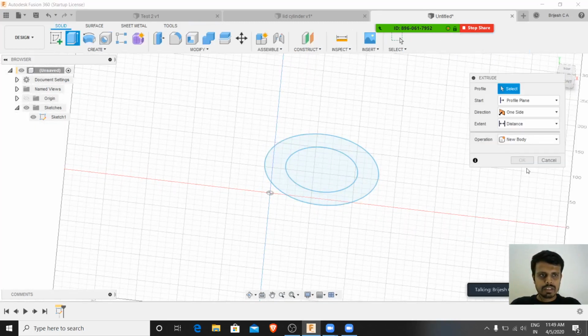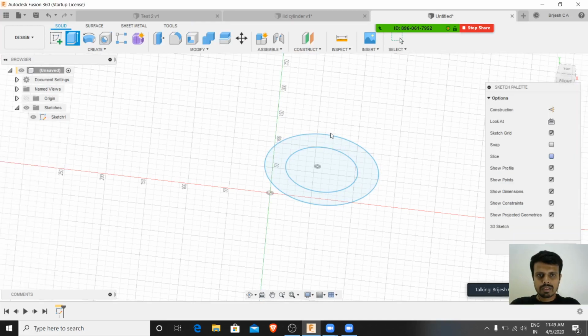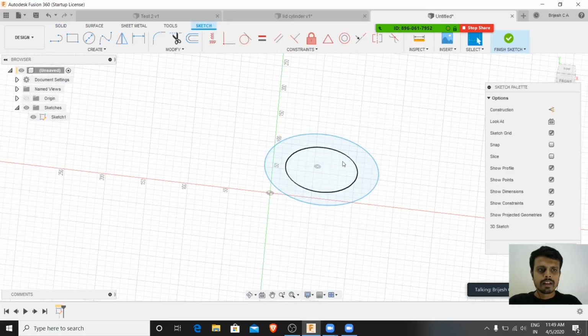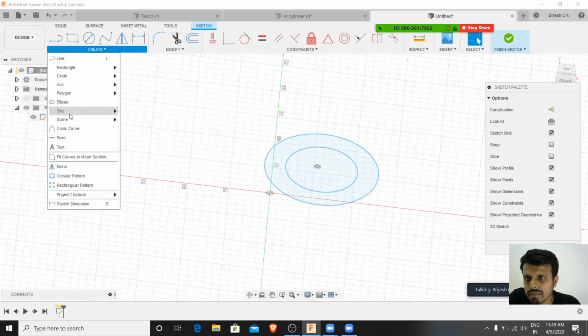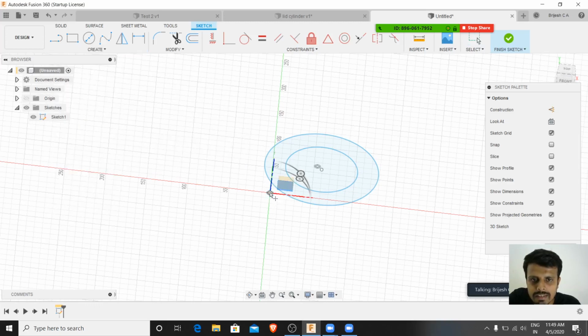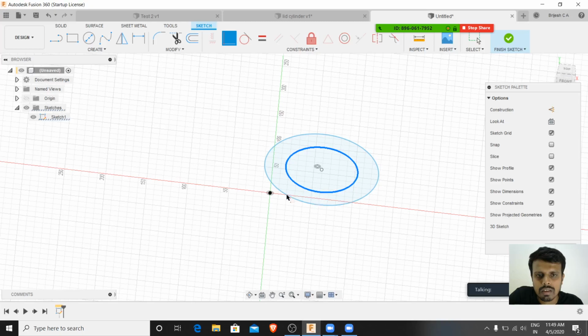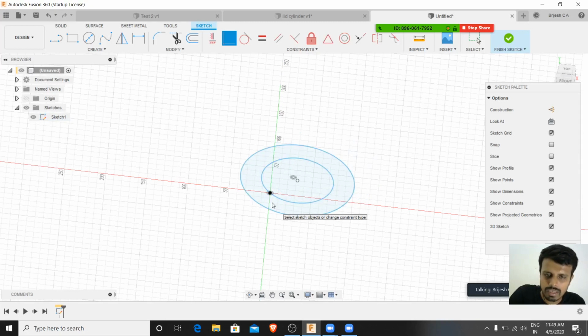I have option 2. You're asking me to move these two circles to the center. Okay. So first, what I do is I just create a point, a point in the center, just to define that there is a point. Now, once this is done, I want to say, where is coincident? Coincident, and this, no, not happening. Concentric.